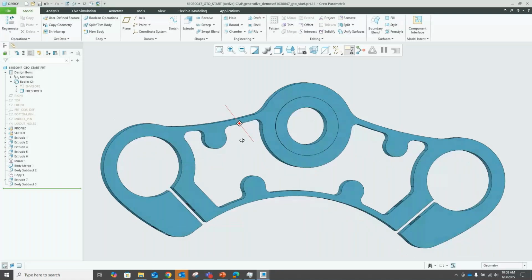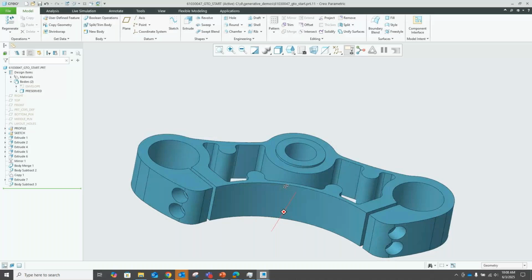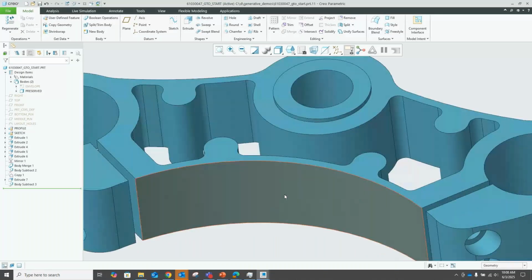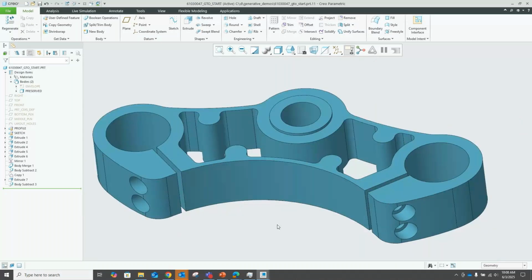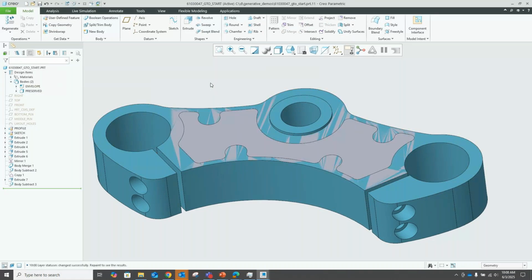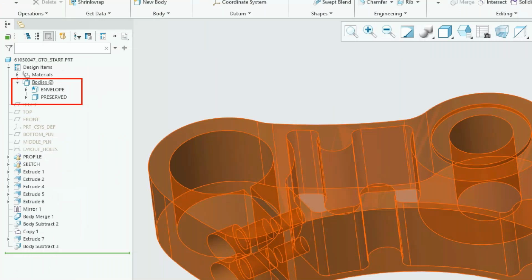So essentially, I'm telling it, can you just give me this area, this volume that I'm sketching around here? This is the area I want some help with, maybe I might ask it to reduce the weight or come up with a geometry that you think based on my constraints, right? Using the AI engine that Frustum has behind the scenes under Creo, right? So it is an extension. It's an add-on extension, obviously. But right now, let me just go reset the status here. I hit a few. So it is using multi-bodies, right? Some of you may know Creo 7, we introduced multi-body, or PTC introduced multi-body, and that's what we'll be using today, right?